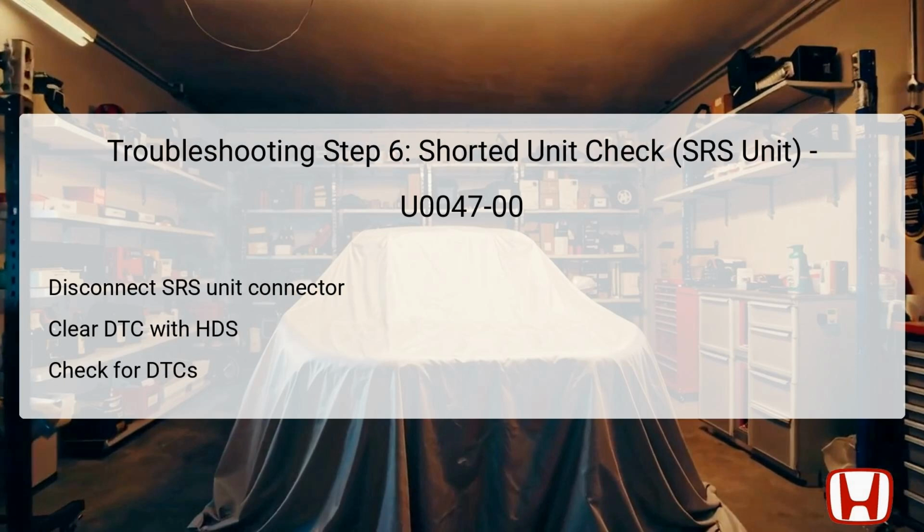Now we proceed to check the Supplemental Restraint System, SRS unit, as a potential source of DTC U0047-00. Start by ensuring the vehicle's ignition remains in the off position. Disconnect the SRS unit connector A, identified by its 39P configuration. This unit is critical for airbag deployment and overall passenger safety.